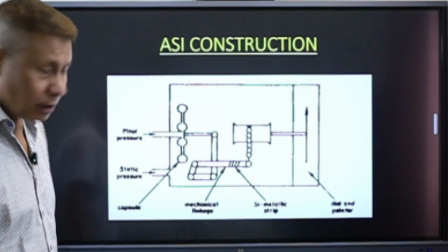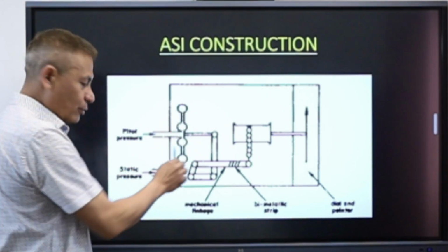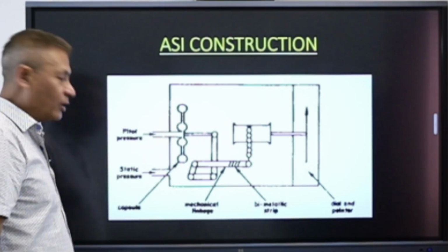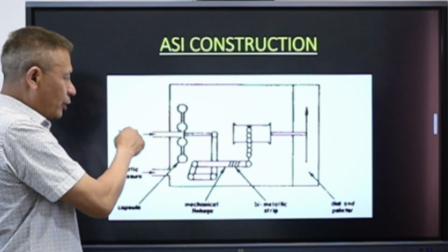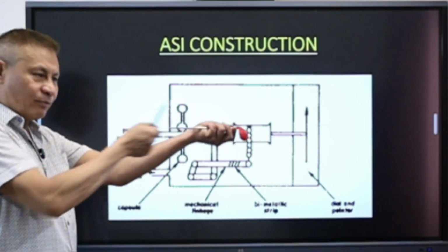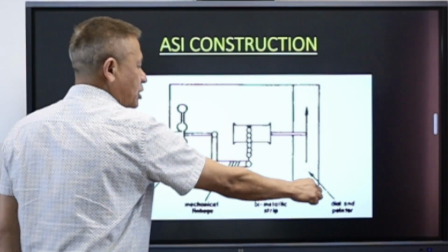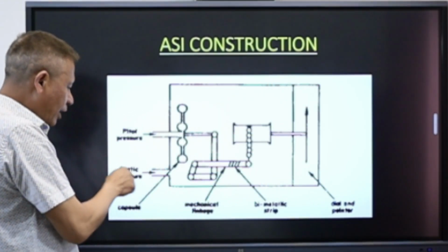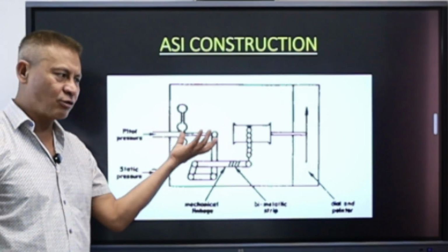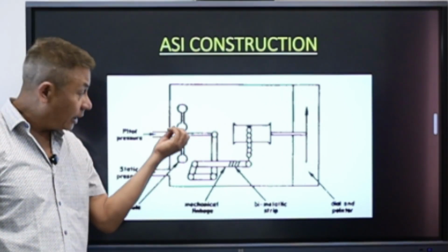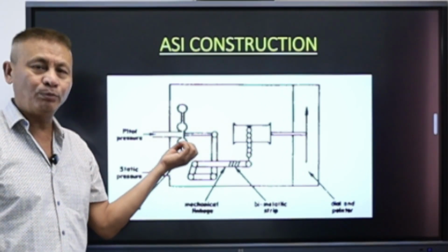So now the pitot pressure which was coming from the pitot head will be fed inside the capsule. Like I have shown you, this was a balloon. In an aircraft, that thing where the pitot pressure is fed is what we call a capsule. So inside the capsule, the pitot pressure coming from this pitot tube will be fed, and this is a sealed casing. In this casing, the static pressure will be fed. So whenever the capsule expands or contracts, it is expanding or contracting against the static pressure. Therefore, we achieve that same formula, that is dynamic pressure is equal to pitot minus static.